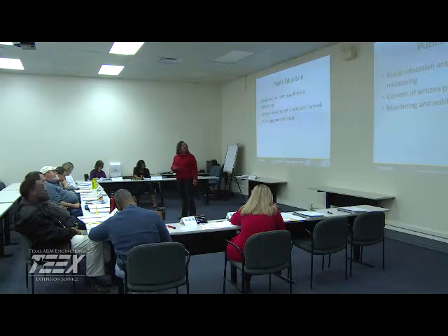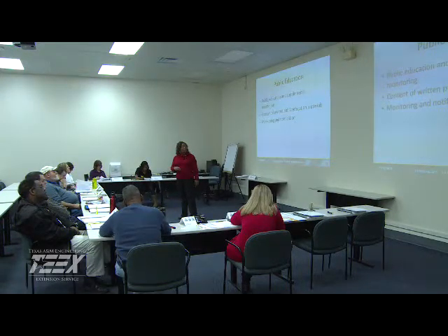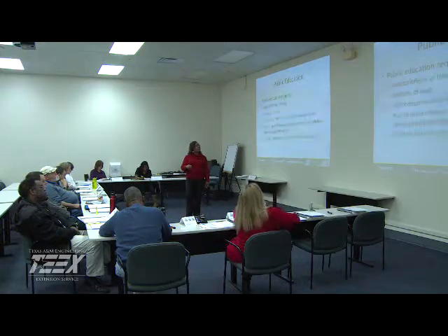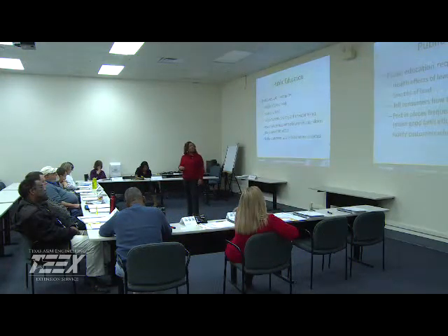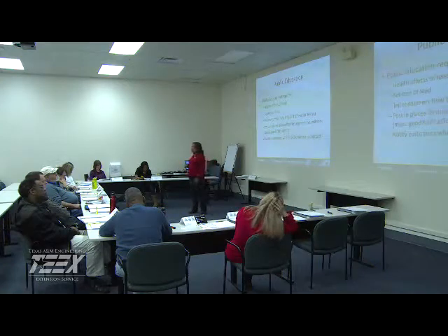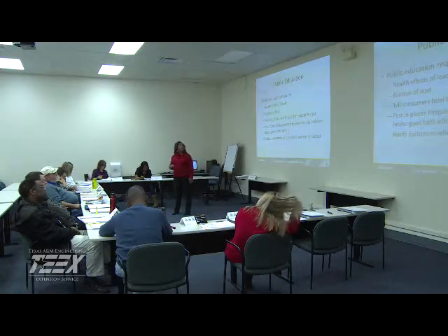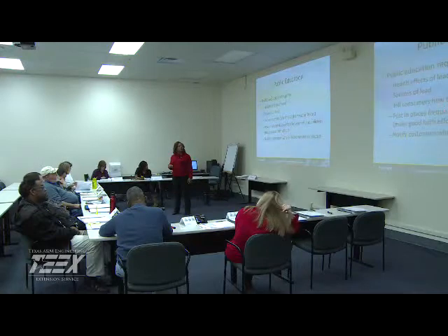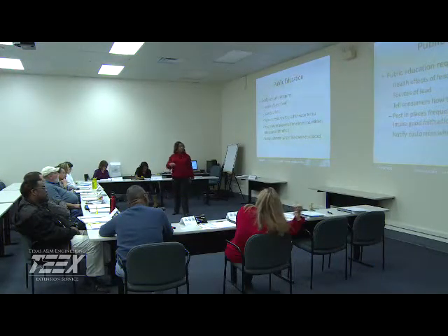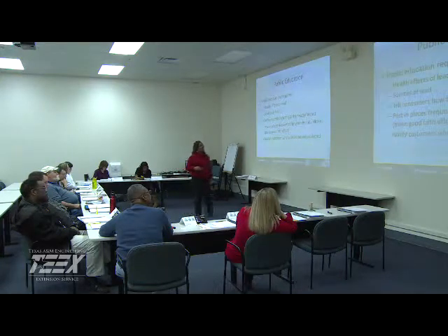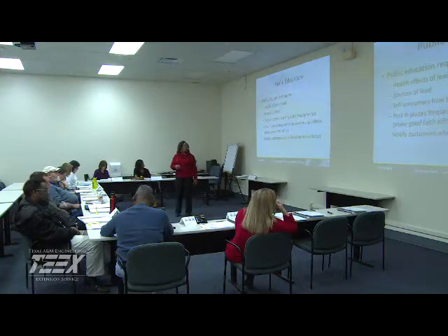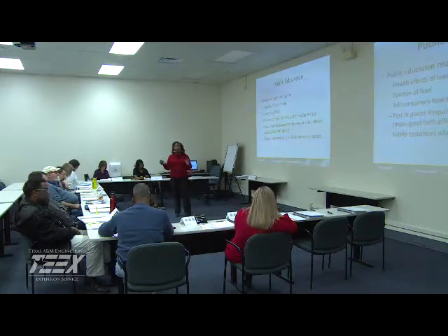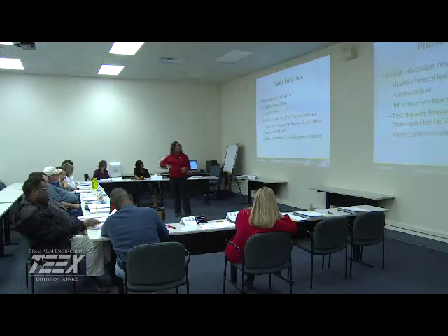All right, public education. The content of what you submit to the public must be written. We're going to tell the public the health effects of lead, which we talked about earlier, the sources of lead, and how to get their water tested. You want to make sure that you're going above and beyond. Good faith effort is the way the language reads: make a good faith effort. Post in places frequented by women and children. Notify the customers where you pulled the sample if theirs were actually higher.